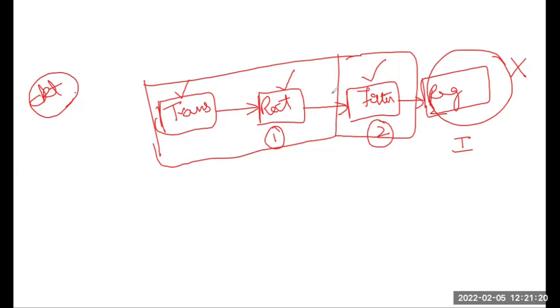After studying the rectifier in detail, we will move on to adding a filter to it, because the filter receives its input as the output of the rectifier. So first we discuss the rectifier, then we add a filter. If I want to draw the circuit diagram, my first component should be a transformer and the second component should be the rectifier part. What do I mean by rectifier here? I mean the component or device that we are using for rectification purpose. And what is that device? It is nothing but the PN junction diode.